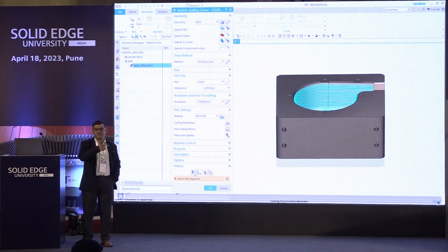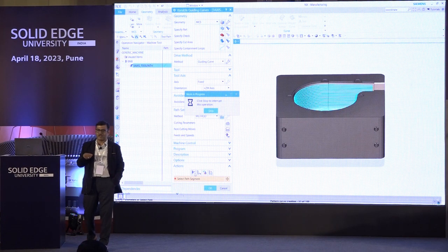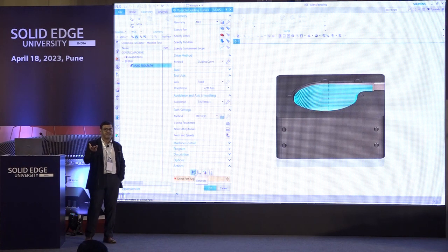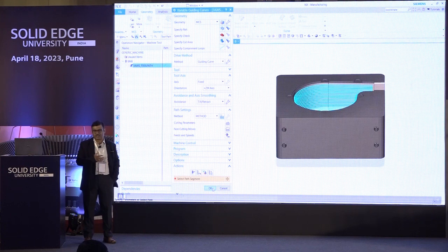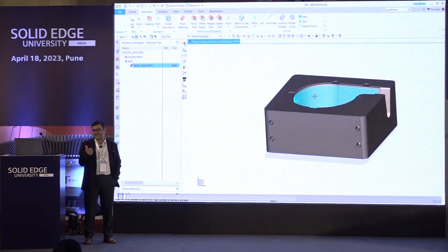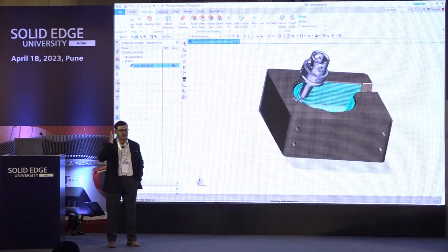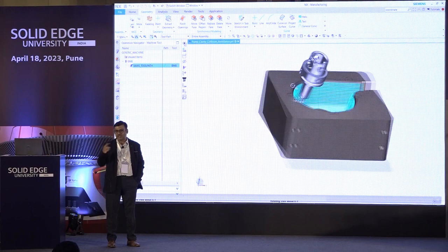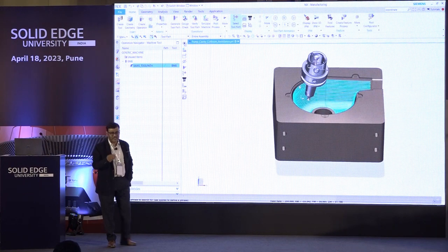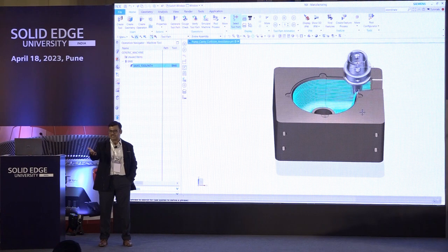Now in that scenario, you can convert a 3-axis toolpath to a 5-axis toolpath when you get a new machine, right? So that kind of flexibility is there in today's world. Earlier we did not have all these options. So take the toolpath, optimize it, and then give the base angle, or what we call a fan angle, and give the lead-in and lead-out angle, let's say a 20-degree tilt. Depending on that, you tilt the tool, and then you can easily convert a 3-axis toolpath to a 5-axis toolpath if you have a machine now.